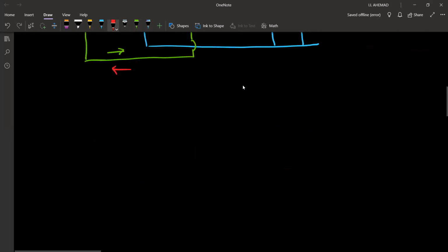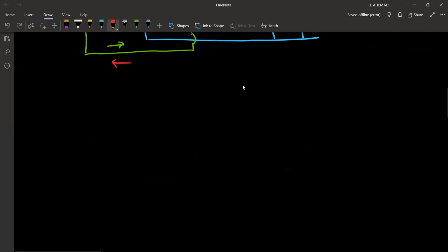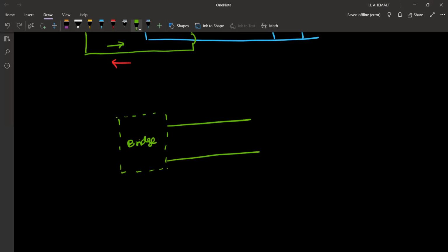We have the bridge. So this is the bridge circuit. And now we are going to get the output. We have the smoothing capacitor. And then we have the Zener resistor. And then the Zener diode. And the load resistor.